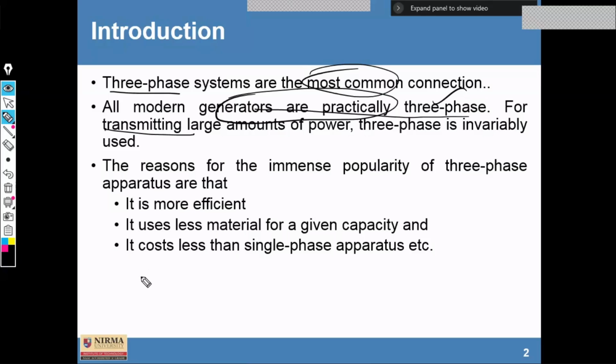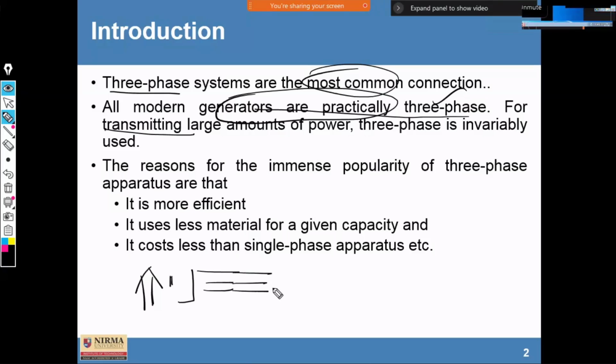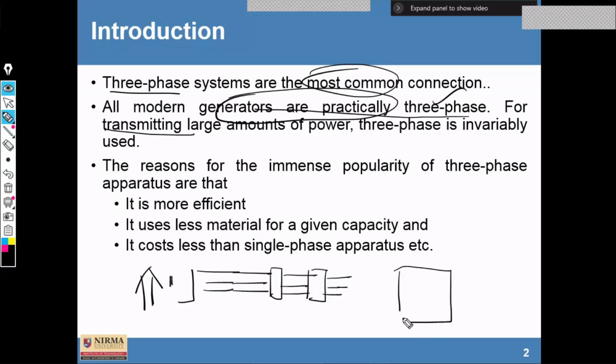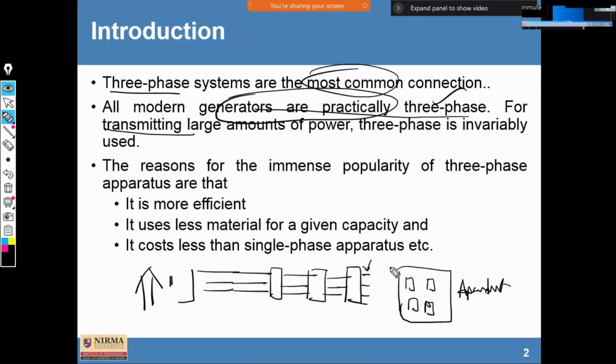Right? So if electricity is generated at a place, it is transmitted through transmission lines in three different lines, and again there are substations and then transmission and again substation and then transmission, and finally at our premises, if it is an apartment, then from this three-phase four-wire system, with R, Y, B and neutral, the different apartments are connected through R and neutral, Y and neutral, B and neutral lines.